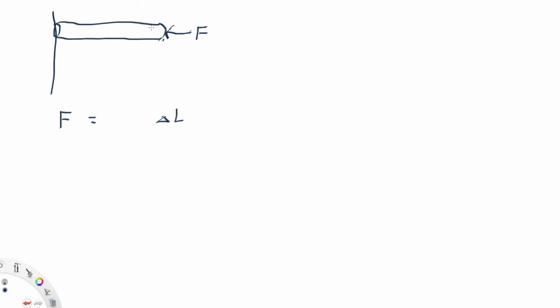And what do we mean by thicker or thinner in this context? Well, usually we talk about that in terms of the cross-sectional area. So larger area means more force required to make the same deformation. What about the initial length of the rod? Is it easier to squish it by a little bit if it's quite long or if it's quite short?